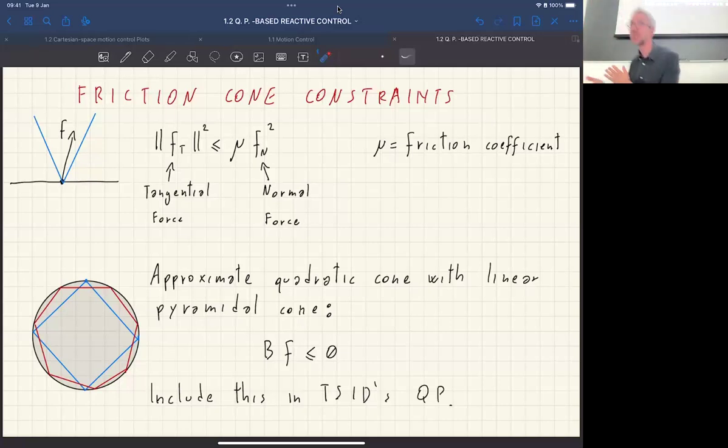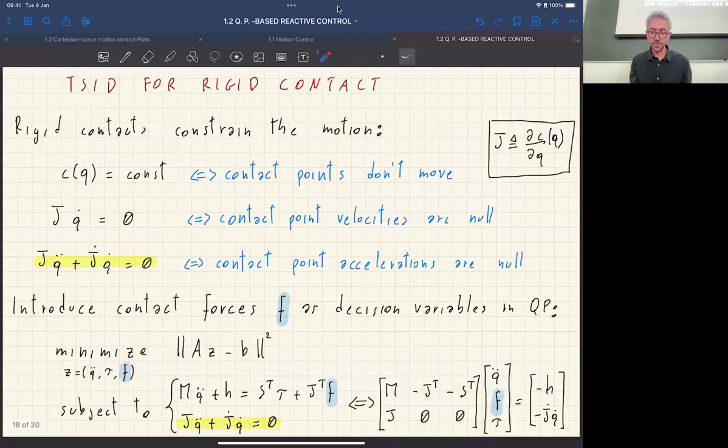You're going to have a mismatch between the physics and what the solver thinks the robot can do. So ideally, you would like the two things to be as close as possible. And this also, to a certain extent, solves the problem that we are using this simplified contact model that says that the contact point cannot move.